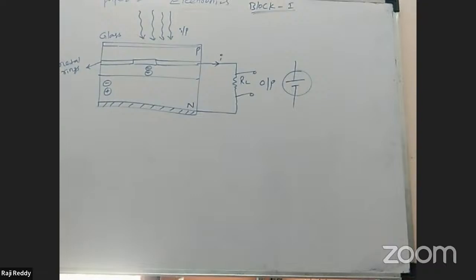The light ray incident on the P region top surface passes through the glass slab and collides with the atoms, so an electron-hole pair can form. That electron-hole pair can move towards the n region. The pairs generated in both the p region and n region can move towards the n region side, as shown in the figure.